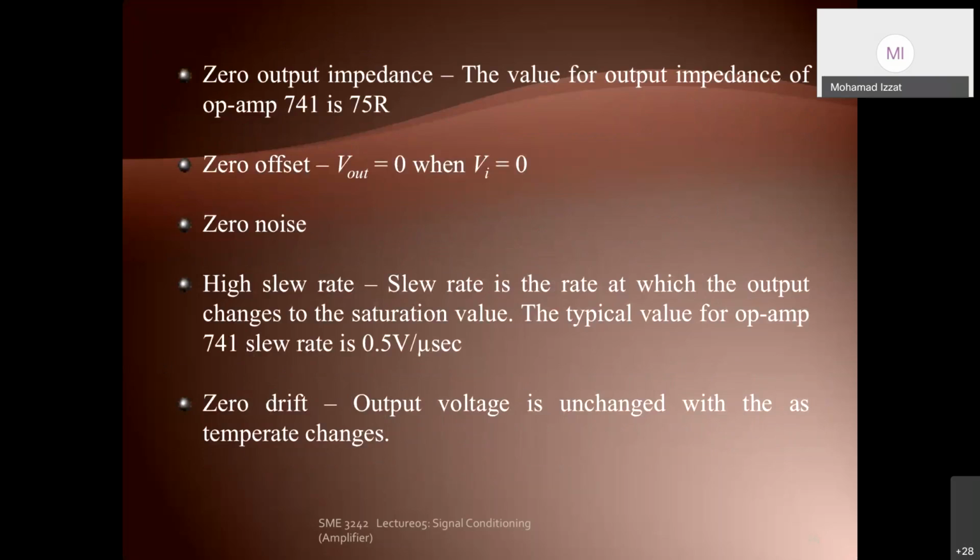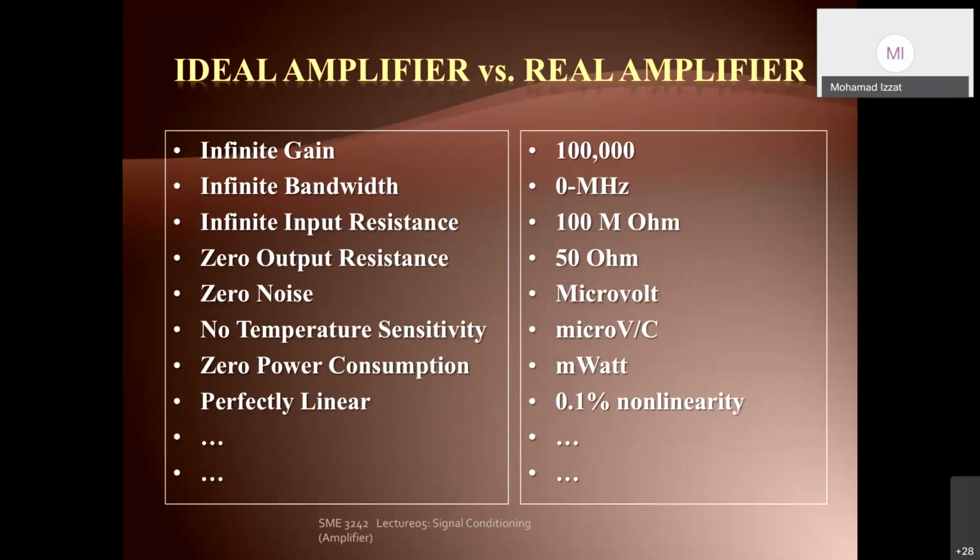These are also the differences between ideal and non-ideal. In this there is a table, which you can see. For example, on the left side you see output resistance is zero. But in the real world, because you are using material like silicon or semiconductor, the atomic structure will always give some kind of resistance. So it is measured in electronics in ohms. For example, also noise: by calculation, there is no noise. But when you construct the circuit itself, you will get something, even in microwatts.